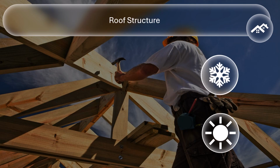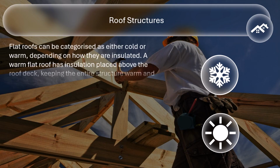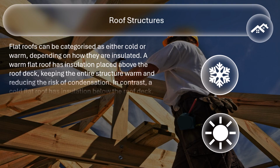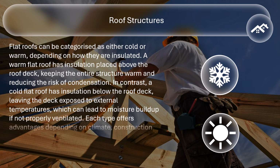Roof structures. Flat roofs can be categorized as either cold or warm, depending on how they are insulated. A warm flat roof has insulation placed above the roof deck, keeping the entire structure warm and reducing the risk of condensation. In contrast, a cold flat roof has insulation below the roof deck, leaving the deck exposed to external temperatures, which can lead to moisture buildup if not properly ventilated. Each type offers advantages depending on climate, construction preferences, and energy efficiency needs.